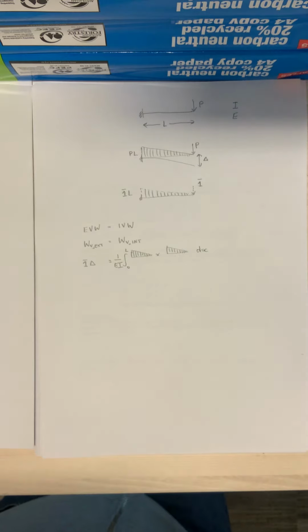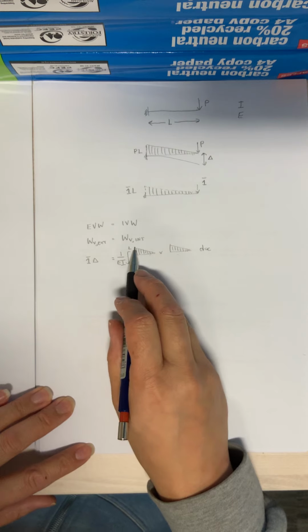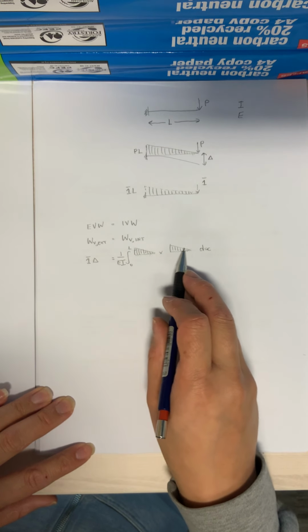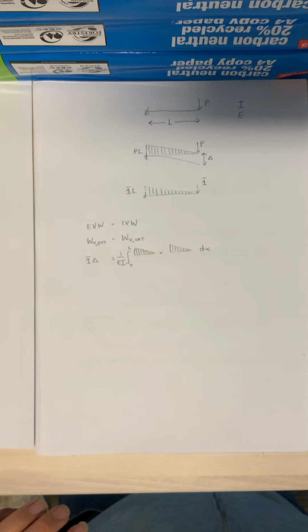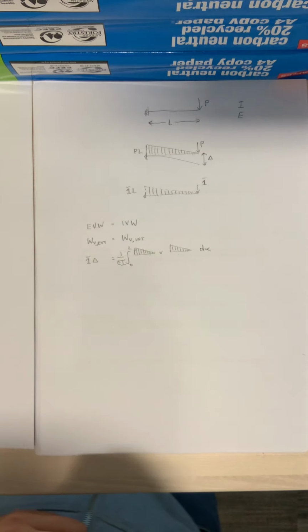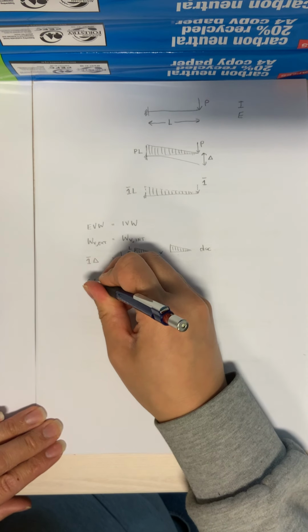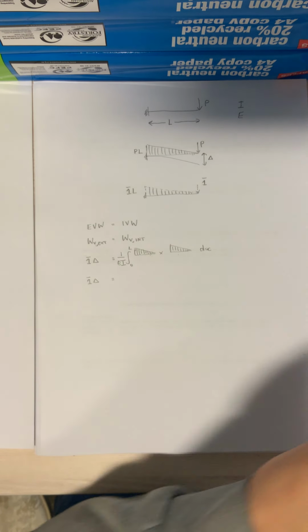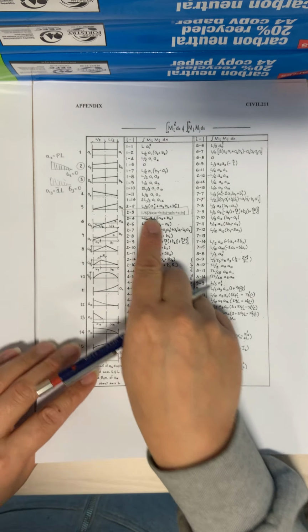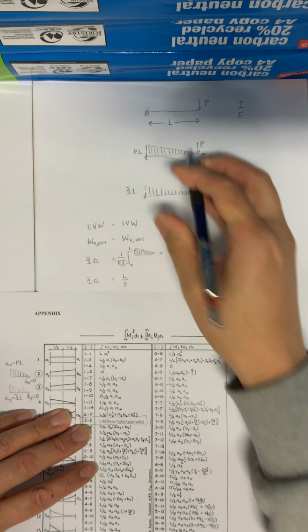So we've got that equation there, which we need to integrate, and you're more than welcome to work out that equation there and that equation there, and just multiply the two equations together and integrate, but you'll probably come up with the same thing. I'm just showing you how to do this quickly. So 1 bar times delta is equal to, going back here, we can see the equation for 2, 3. The length of the member is L, so it's just going to be L over 6.